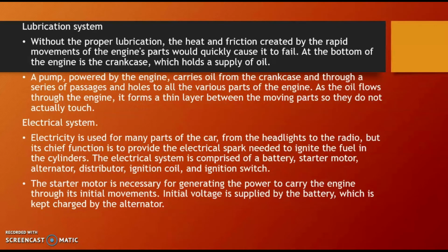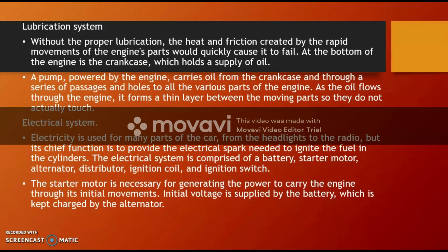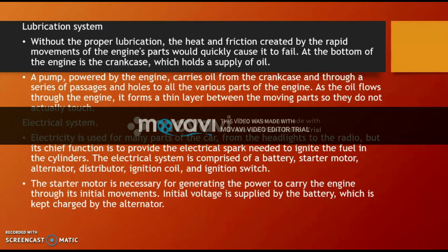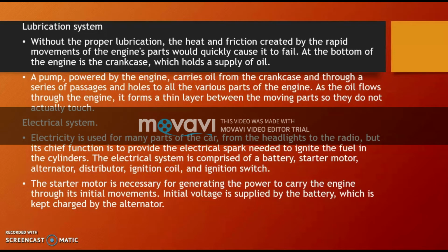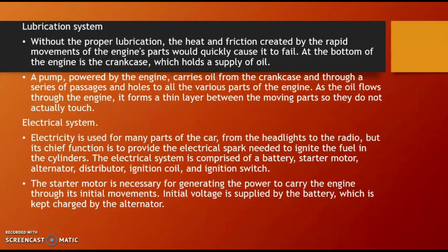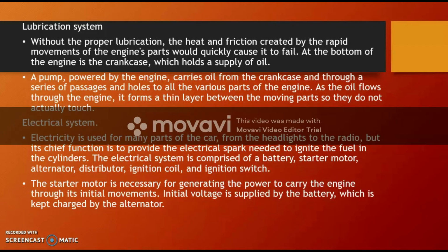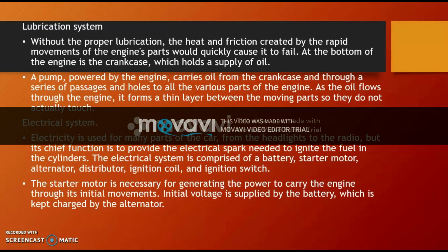For the lubricant system, without proper lubrication, the heat and friction created by the rapid movement of the engine's parts will quickly cause it to fail. At the bottom of the engine is the crankcase, which holds a supply of oil. The pump powered by the engine carries oil from the crankcase and through a series of passages and holes to all the various parts of the engine. As the oil flows through the engine, it forms a thin layer between the moving parts so they do not